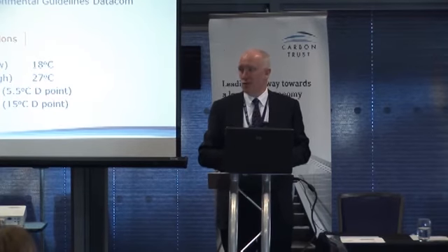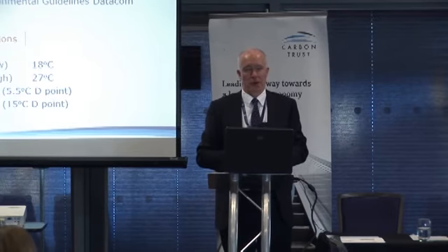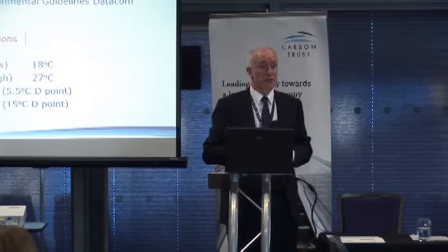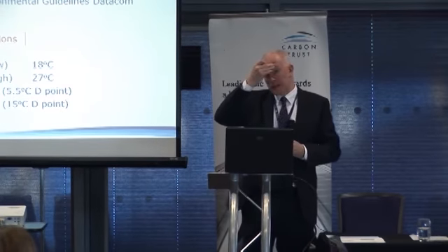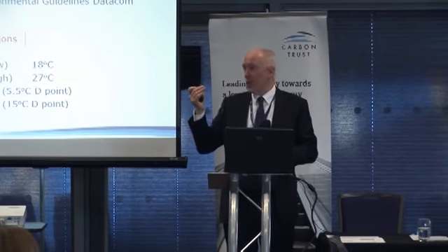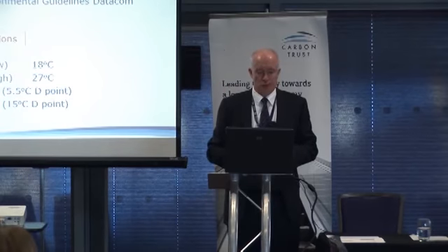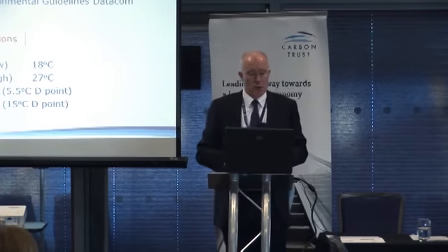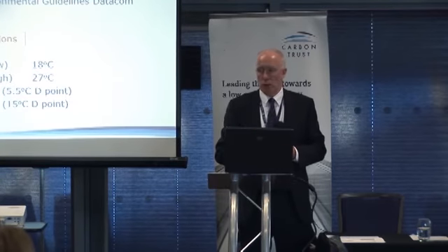You can push the temperature up as high as 27, stable on temperature, and the majority of computer systems will be fine with that. So again, that perhaps supports what you're doing there. You've gone from 18 to 25, which is fantastic. Huge amounts of savings by doing that. So we must try to get the IT staff, who sometimes like to be in a chilled environment for personal reasons, to realise that actually we are talking about 25, 26 degrees centigrade. It's quite correct for a computer centre. On ASHRAE standards, the low humidity is down at 40%, the highest level of humidity at 60%, for a major data centre where we want to control humidity.